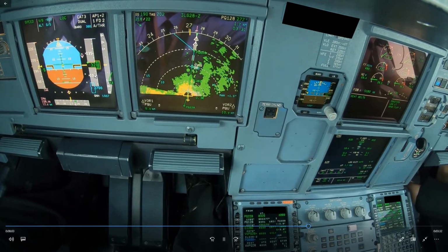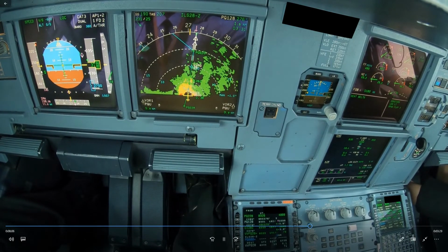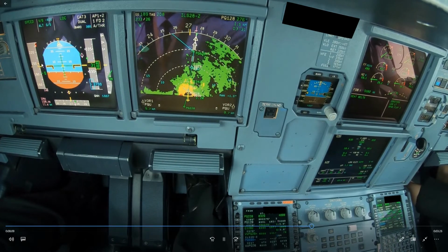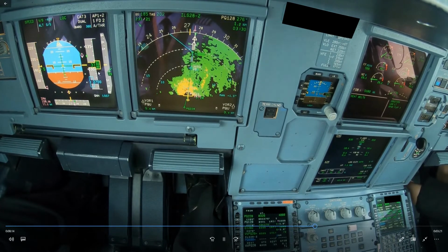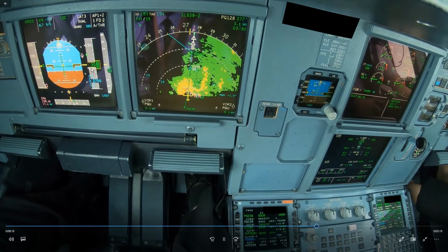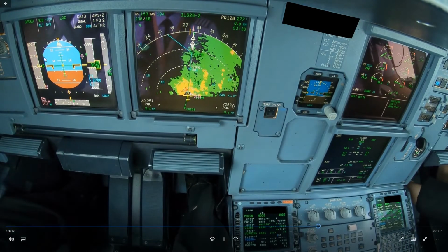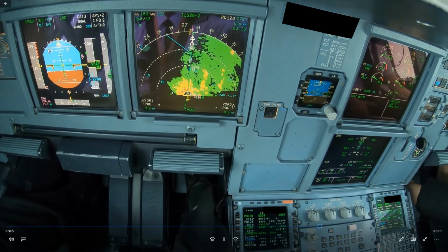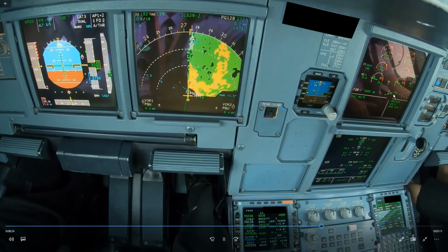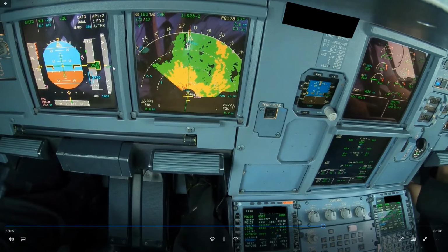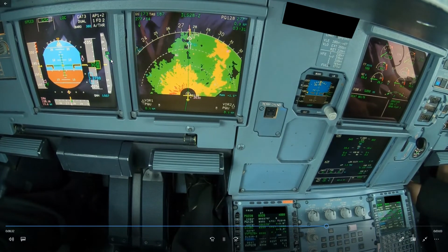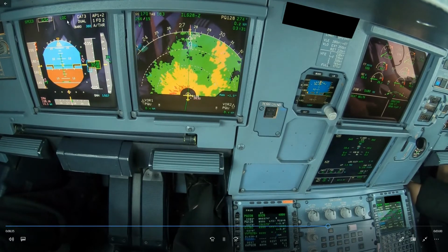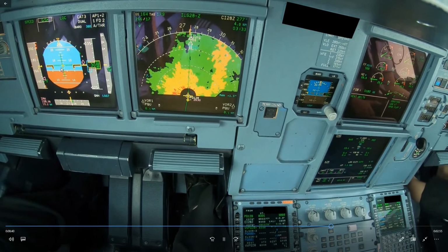And then when you pass 3,000 feet, and make sure that you are below VFE next, because here you can see it's a bit turbulent. But when you pass 3,000 feet, right there, then you select flap 2 and let the aircraft balloon onto the glide slope. And if the speed is fast, you can also modify the vertical speed to make sure you are below VFE next. So there's flap 2 selected. The aircraft will balloon. You see that here. It will climb a little bit. It will always balloon about 500 or 600 feet a minute up. It goes into glide slope star. We set the go-around altitude. And down we go.